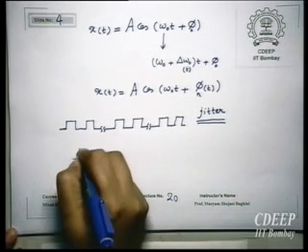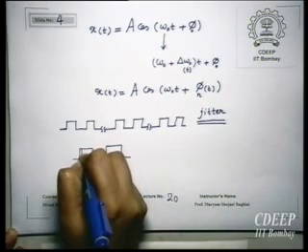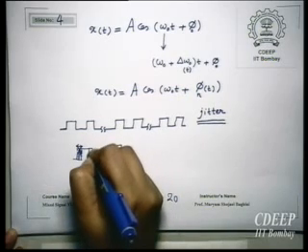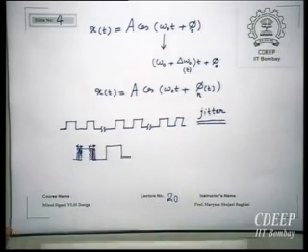So what you will observe on the oscilloscope will be something like this. You will see this is blurry. This edge is blurry. This is because the frequency, or effectively the phase, of this signal is changing with time. So this is called jitter.